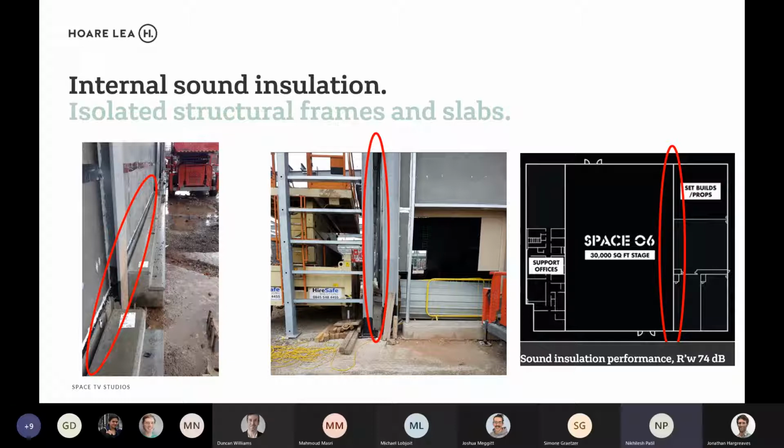So very early on, it is the responsibility of the acoustician to comment on the structural side as well, to tell them that, as a means of avoiding flanking, we need to have different frames completely separated from the sensitive acoustic structure. So as you can see, this is one example where the acoustician has to pitch in and comment on other disciplines as well, to make sure their design does not interfere with the acoustics.